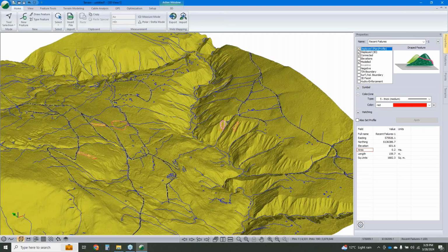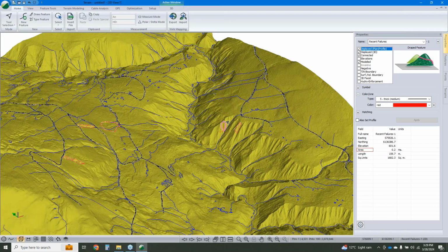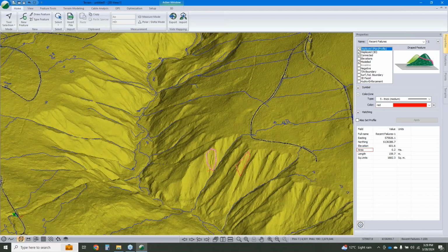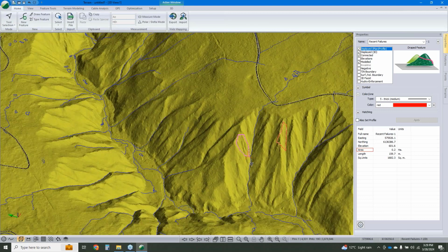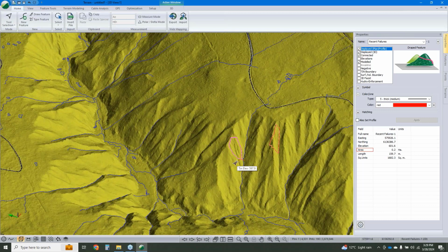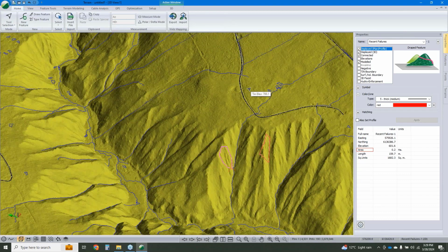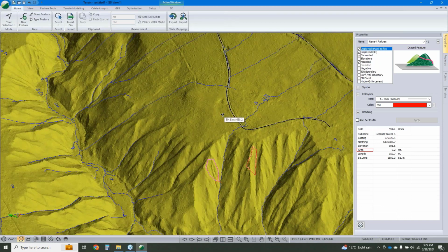And so aside from just figuring out how large you should make your culvert based off drainage area and flow path, we can also assess how we're interacting with the terrain. And here we're going to kind of look at it from a context of existing infrastructure. With that, we have the benefit of hindsight, and then we'll talk about this as we get into our design stuff. So this feature, recent failures -1, I'm going to calculate a drainage area to this point.